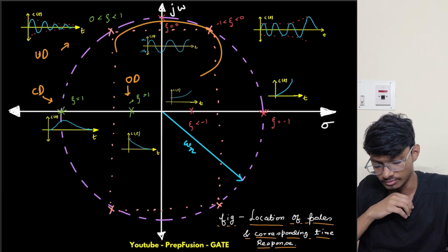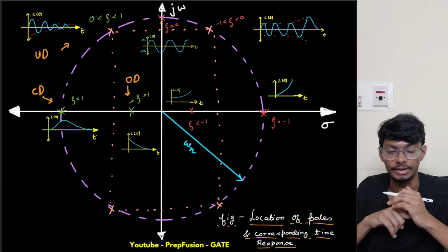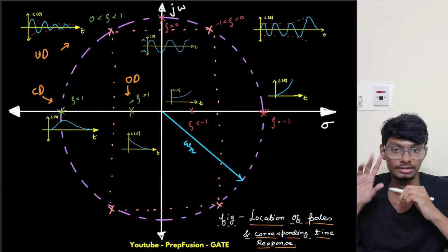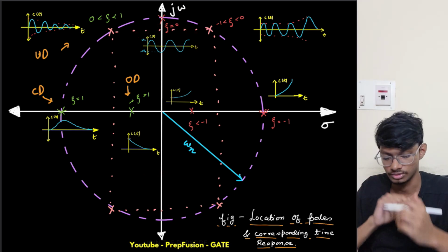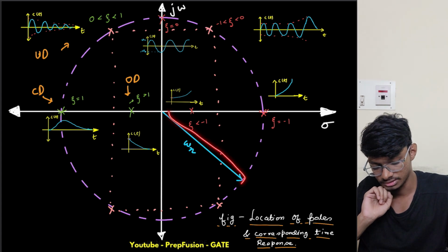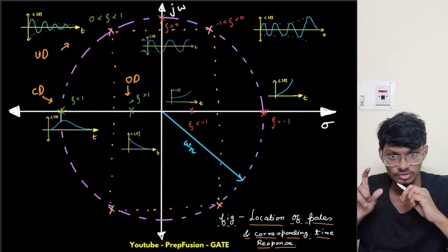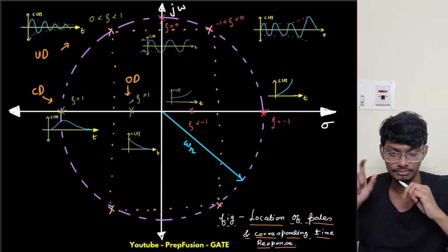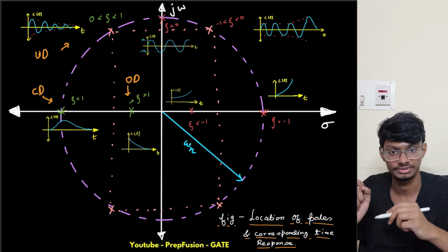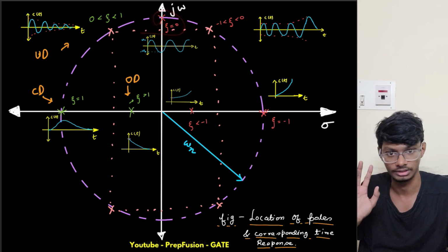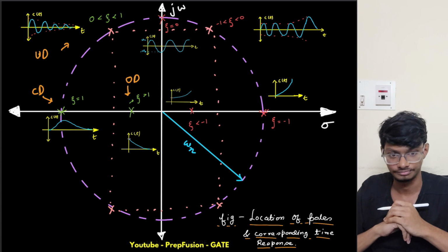Okay. So, and what is this? This is the undamped nature. What can I tell about the poles of undamped? The poles are lying on the imaginary axis and are conjugates of each other. Like this is a circle of radius omega n, and on the imaginary axis it becomes omega n only. So the poles will be plus or minus j omega n, and omega n is the natural frequency of oscillation. What does this represent? No damping is present. That's why zeta is 0, right? Hence it oscillates at the natural frequency of the system.